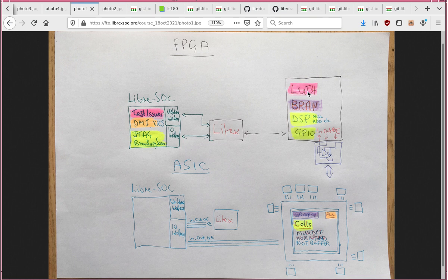And likewise, you get a different cell library, in effect, so the Yosys program understands that you have LUT cells, BRAM cells, DSP cells, GPIO cells, PLL cells, which it is designed to rewrite the BLIF file to correspond to those resources, and that's then picked up by the nextpnr-ecp5 tool.